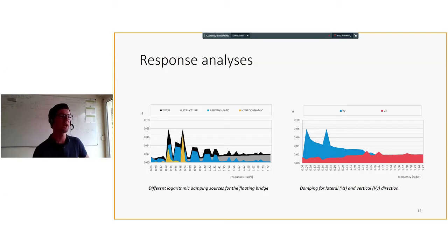So we actually sometimes rely on the wind damping. And this is kind of an interesting phenomenon. If we have a scenario, a combination where you have no wind and maybe some swell loading, you can get quite big excitation of the bridge because you don't have the damping there for the vertical modes. And this was observed during this work.